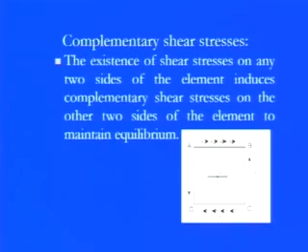Now come to another point in the shear stress, that is complementary shear stress. As we have discussed, the shear stress is a plane stress. Plane stress means it is always acting in either the xy, yz or zx plane, as we have seen in the previous part. You see here these 3 shear stresses are there, so tau xy, tau yz and tau zx.